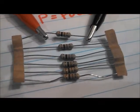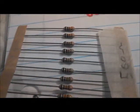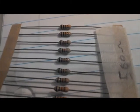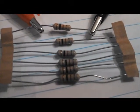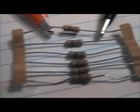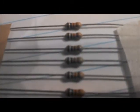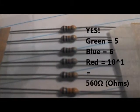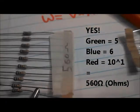Now in these cases you have on the left a series of bands which indicate the resistance. These are the quarter-watt resistors, and they're listed as 560 ohms. This is the larger one, and it's a brown, black, brown, and I believe that this one is a green, blue, red. I'll double check those later, but it's those color codes that actually determine the resistance.